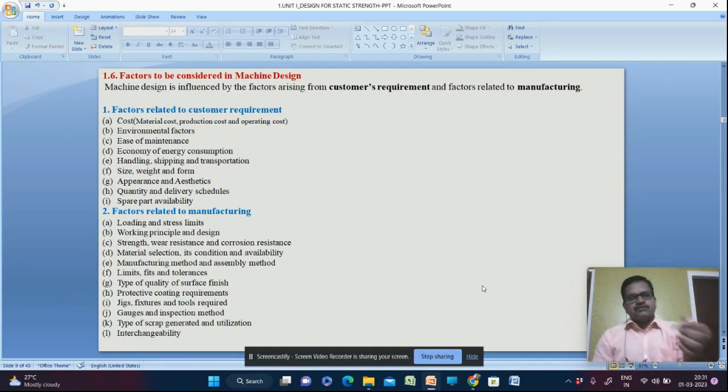Here you can see this pen. When the cap is placed over the pen, it is very easily going inside. But when it goes to a certain extent, you need to have a push. That means until this period it is having clearance, and then it is having some difficulty. So this is called transition fit. And when in entirety the pen cannot enter the cap's hole, then that condition is called interference fit.